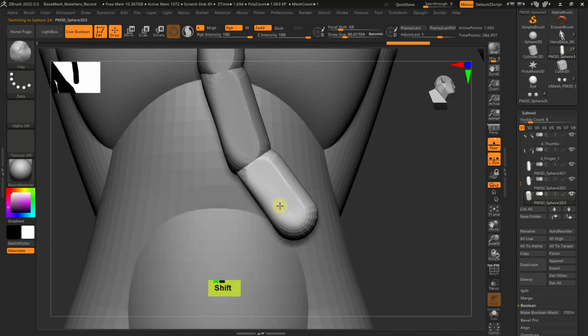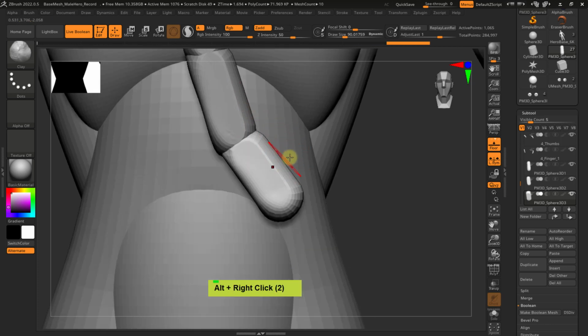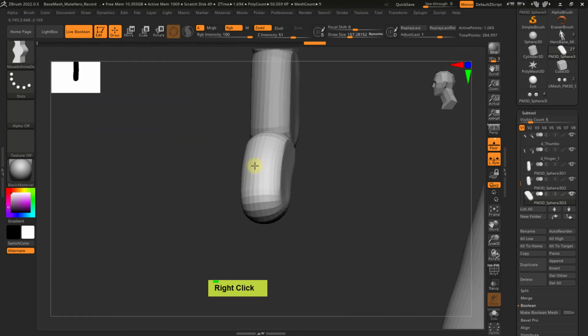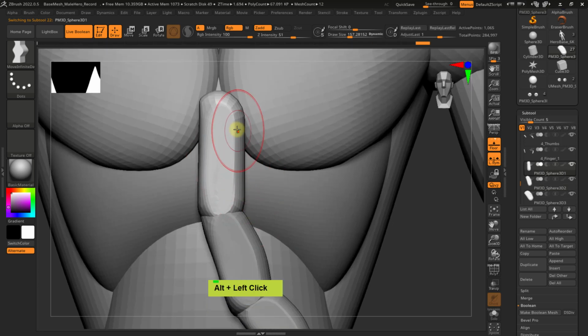And okay, I also want to change the silhouette, so I'm using a brush. Now, to make sure that the whole mesh is moving, I like to use the BMN. That's the Move Infinite brush, and that way I can be 100% sure that everything is grabbed. Okay, it's a nice and even grab. If you're just using the simple move brush, it may not work as well as this one. Okay, so here we definitely have a little bit more belly. The palm is coming in, but that's it.